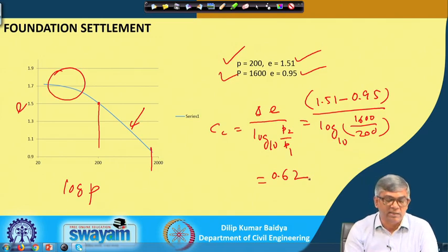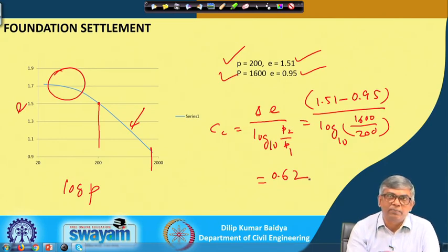The first job is done. Either you can take a graph sheet, generally you have to take a graph sheet when you are in the exam hall, because you may not have the plotting facility there, or you can use Excel when you normally practice, and then you put the values and fit, and you will get a straight line. By observing the curve, you have to first decide whether it is an overconsolidated or normally consolidated case. Normally consolidated case, how to know?